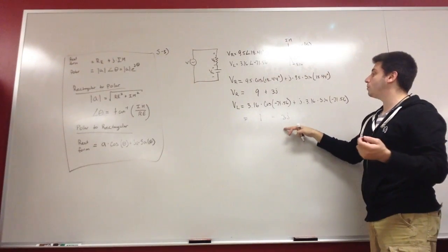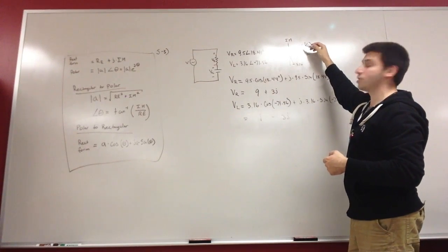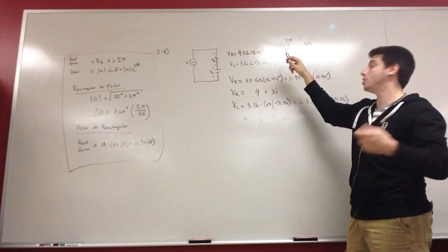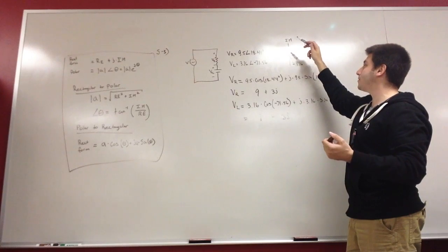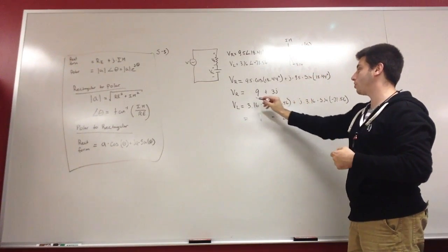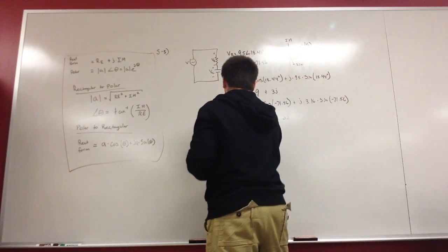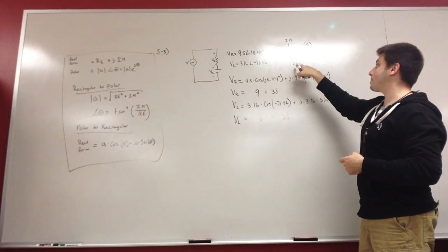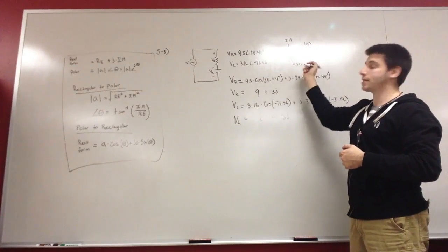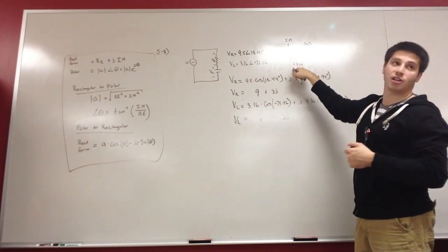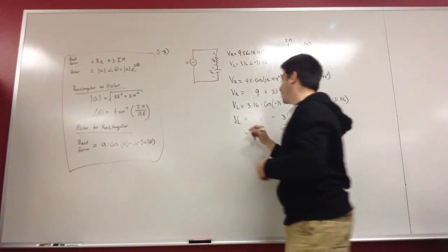We can do a sanity check by looking at our signs. Because V sub R is in the first quadrant, we know that we're going to have a positive imaginary component and a positive real component. Looking at this, we have both. Looking at the rectangular form of V sub L, we'll have a positive real component because it's to the right of the y-axis, but we'll have a negative imaginary component, and we have a negative imaginary component right here.